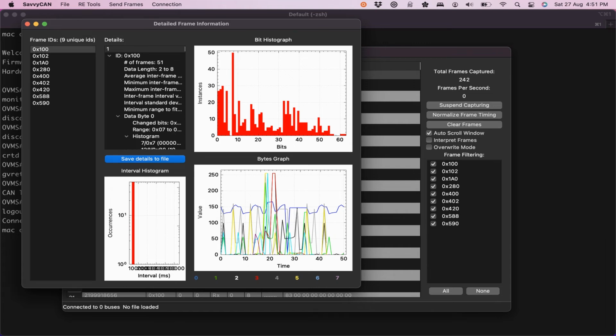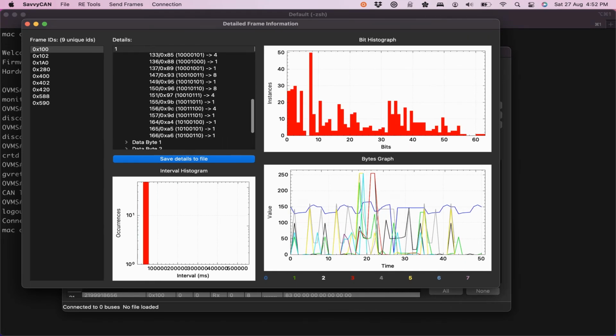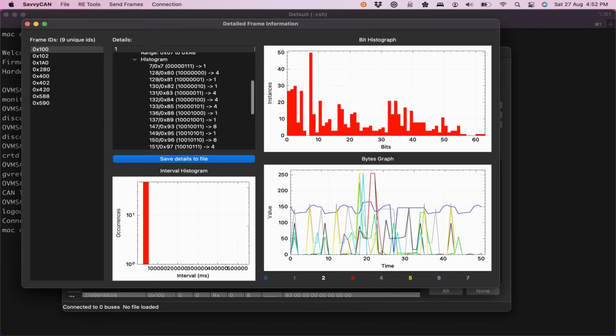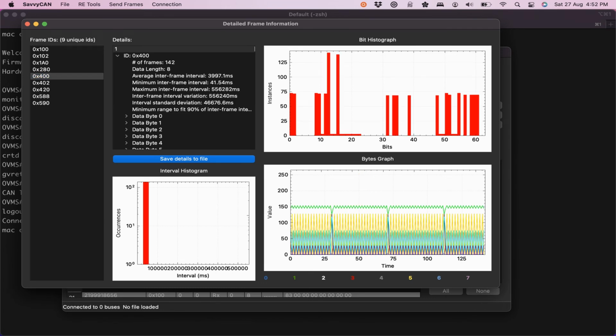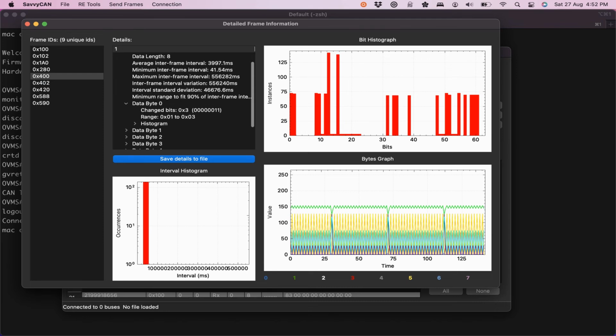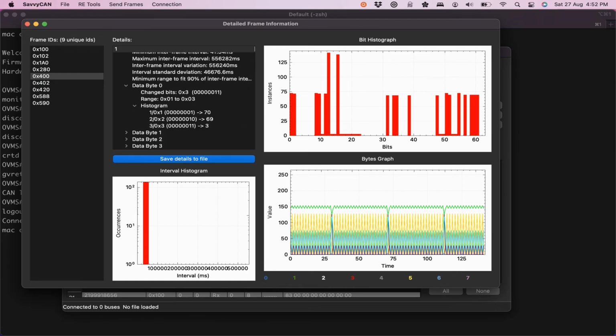It is not uncommon for CAN messages to be multiplexed, with one particular byte being an index for a sub-message type. For the Tesla Roadster instrumentation CAN bus, both ID 100 and 400 use the first byte as just such a multiplexer. In such systems, the meaning and interpretation of the remaining bytes of the message is dependent on the multiplexer byte, so identifying such multiplex data is often the first task in reverse engineering a particular CAN bus.